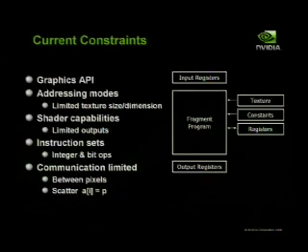The next input you have is texture. These are those images, or decals, you want to apply to triangles or pixels to determine their color. In a GPU world, in general purpose computing, this is our memory. Basically, we have a whole bunch of memory stored as images on the graphics hardware, and we read from that memory. There's a set of constant registers, which are basically fixed constants and are cheap. And of course, some general purpose registers for doing your computation. The result of the fragment program gets written into an output register, and when the program completes, whatever's in the output register becomes the color on the screen.